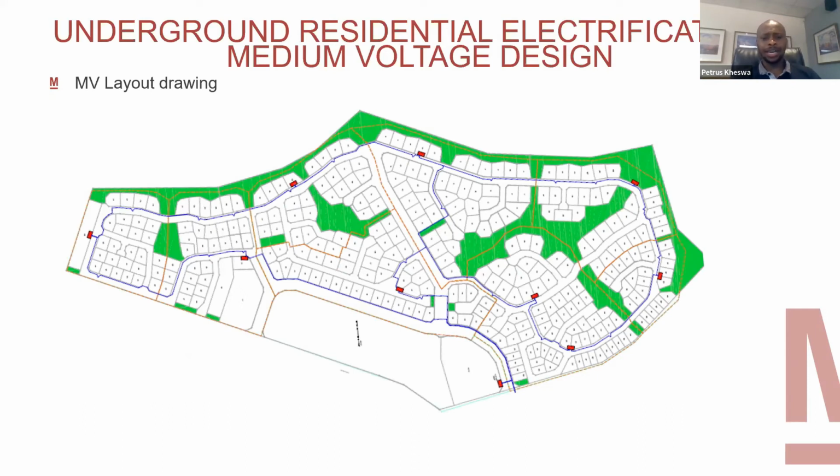This is just a typical layout of our MV network. As you can see, this is one of our developments that we did around Johannesburg. It was an upmarket residential estate, and I think the total number of units there was about 450 or so. We have mini subs, and from the mini subs we have the MV cable. In this development, the substation was on the western side. We installed two feeder cables from the substation, and those two cables were in a ring, so that we have redundancy within this network. Then we placed the mini subs strategically so that we can provide the required load to all those single stands.